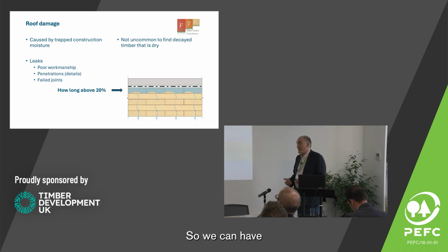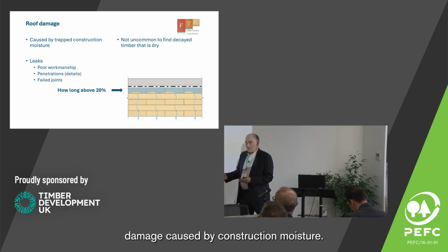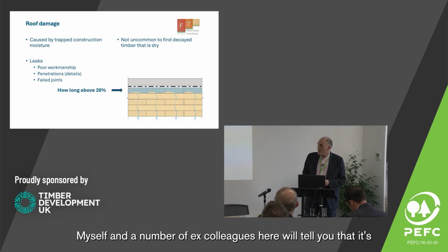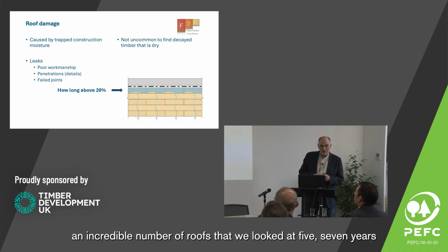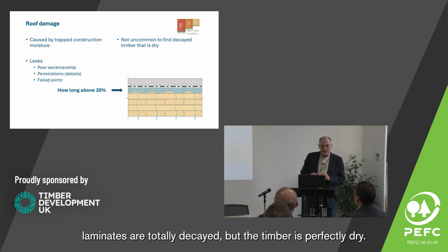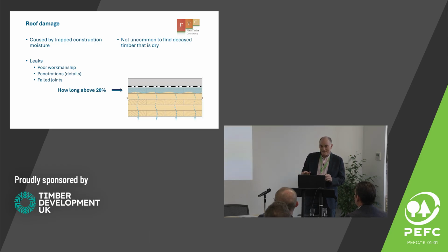So we can have damage caused by construction moisture. Myself and a number of ex-colleagues here will tell you that it's an incredible number of roofs that we looked at 5 to 7 years after being constructed, where the top laminate or sometimes the top 2 laminates are totally decayed, but the timber's perfectly dry. Okay.